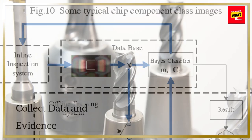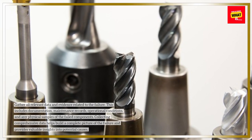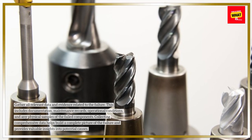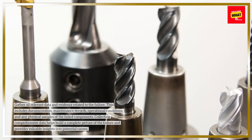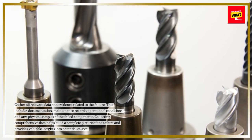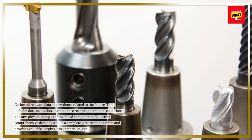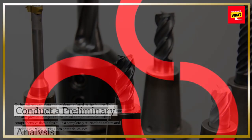Collect data and evidence. Gather all relevant data and evidence related to the failure. This includes documentation, maintenance records, operational conditions, and any physical samples of the failed components. Collecting comprehensive data helps build a complete picture of the failure and provides valuable insights into potential causes.